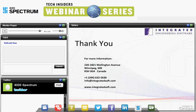But lots of software enables you to say, if I want to play something back later, so for example, if I want to build models, set them up, get them ready to analyze, but understand that the analysis itself might take some time, I can record a batch that'll open something, tell it to solve, tell it to make a certain number of plots and other calculations, forces and torques and the like, and to save the results somewhere, record another batch to do another one, and so on, and I can then play that back later.